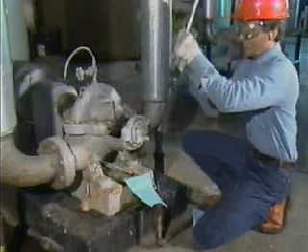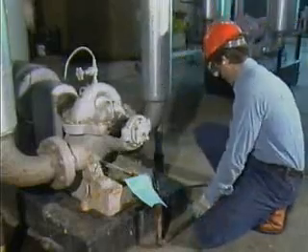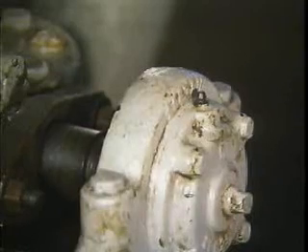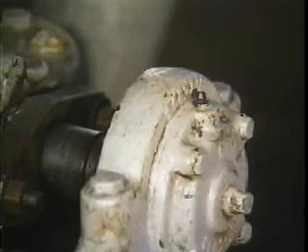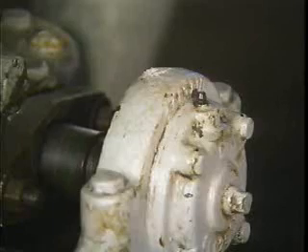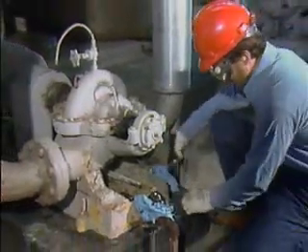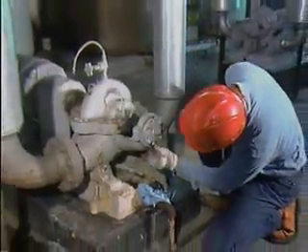Next, disconnect the grease gun from the fitting and wipe the fitting clean. Then, allow the machine to run for a few minutes with the drain plug still removed. As the machine operates, excess grease will be forced out of the drain hole. After a few minutes, wipe the drain plug clean and put it back in the drain hole.